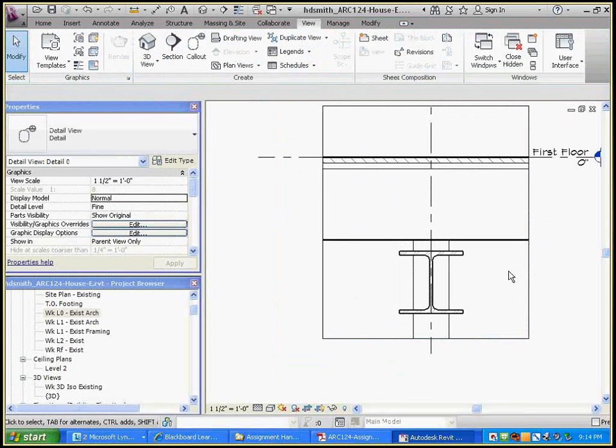So here's where we get into something that we're just drawing in a detail only. We're not going to draw this in 3D. And when you do detailing in Revit, you're drawing basically two-dimensional line work and filled regions and even components that are just flat, stuck onto the view. Remember how I said at the beginning of the class, before we did assignment A, when you've got a view, you've got a pretend kind of pane of glass in the view, you've got annotations and detail lines and detailing that's just in that view.